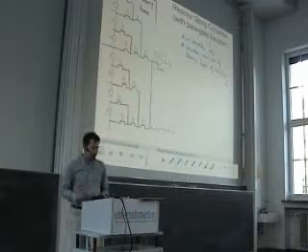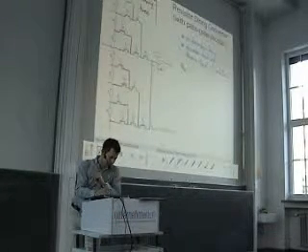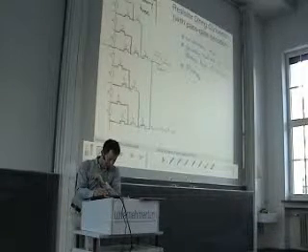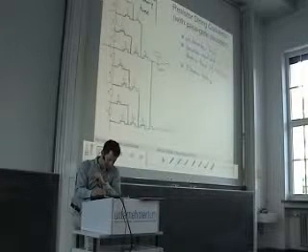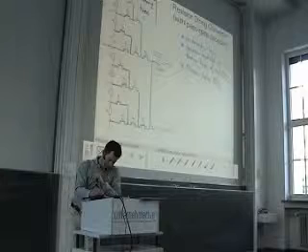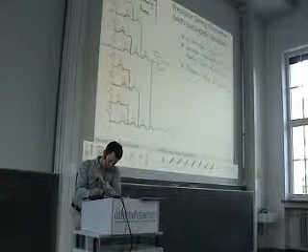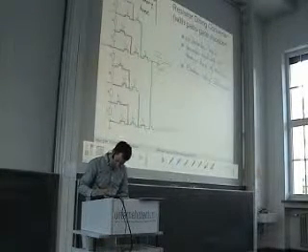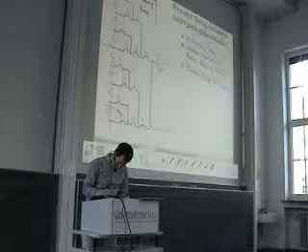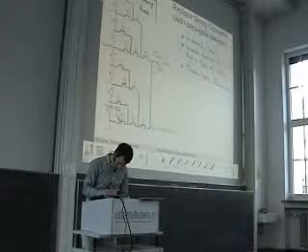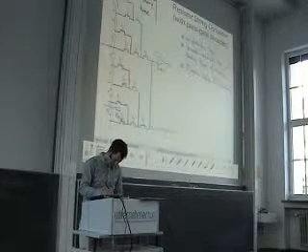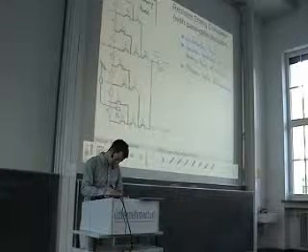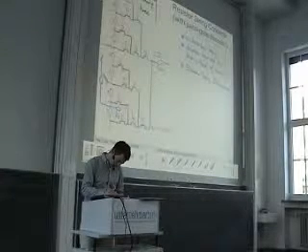Then again, we can use the ELMO delay to estimate the settling time of this DAC. So we can make an ELMO delay estimation. If we again assume that we enable this path, then I have here the parasitic on resistance of the transistor. Here I have the effective resistance of the complete string. So we have here our string.